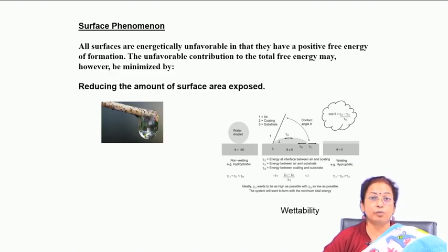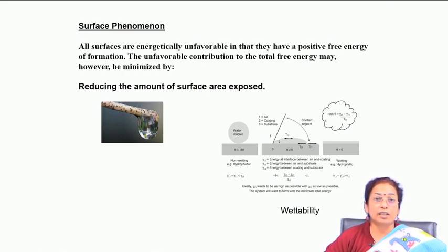Among the different phenomena influenced by surface energy is droplet dimension. When you pour molten metal, it falls in a droplet-like fashion. Similarly, when you prepare synthesized powder by water atomization or gas atomization, its shape is always spherical, because a spherical shape has very low surface energy relative to its very high surface area. So one of the important phenomena related to surface energy is droplet size.